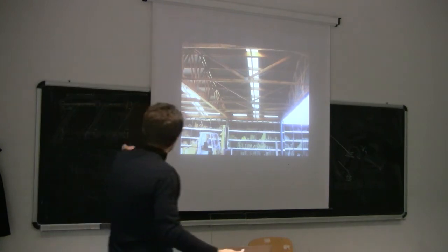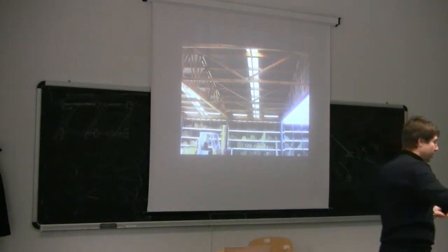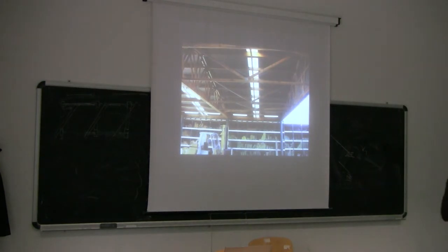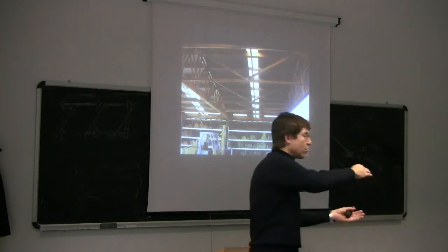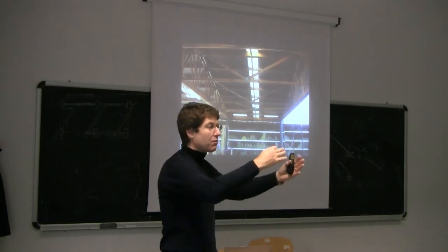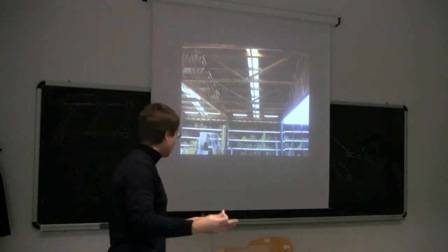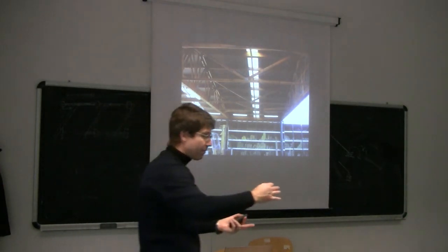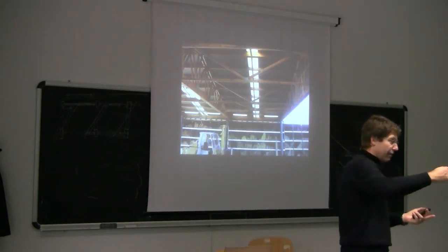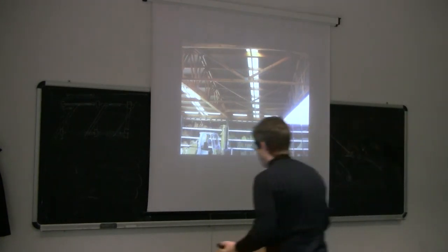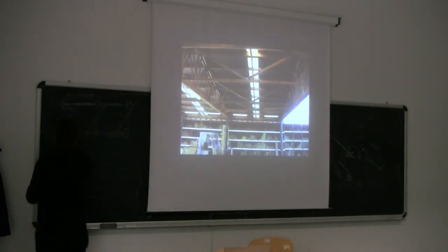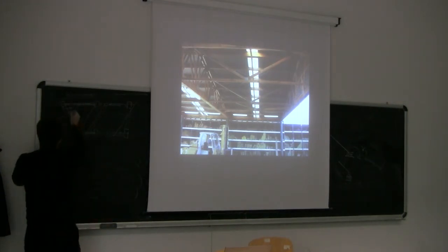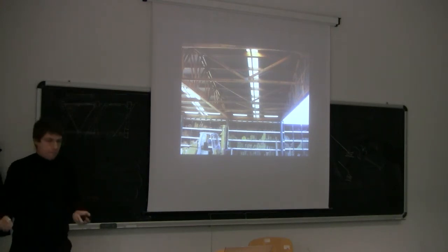So in order to make sure that we prevent this rotation, we have to have one member which has not only axial stiffness, but also bending stiffness. So a truss system like this, as a global truss system, not only provides lateral stiffness, but also rotational stiffness. Because once you do a system like this, now there is no way that this can rotate freely. This could rotate only if this one is going to distort, to deform too much.